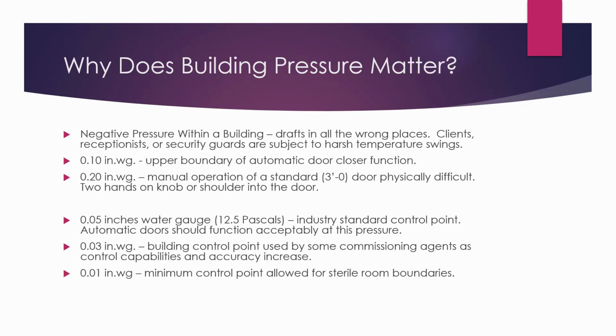So why does building static pressure matter in the first place? Negative pressure within a building causes drafts in all the wrong places. Clients, receptionists, security guards are subject to harsh temperature swings.